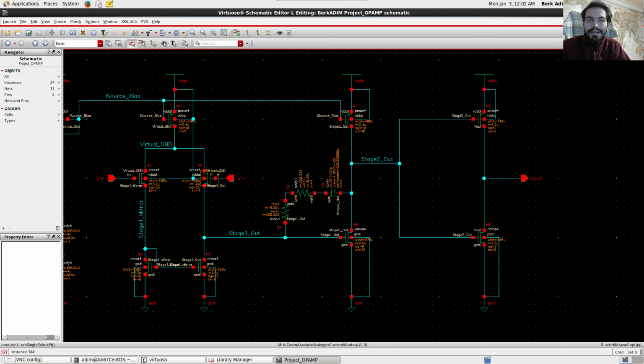Well, but our circuit cannot instantly respond to that. So this transistor is still at 5 volts gate voltage, and it is actually still closed. So where could it draw its current from? Turns out it actually draws its current from this stage through charging this capacitor and then onto itself.